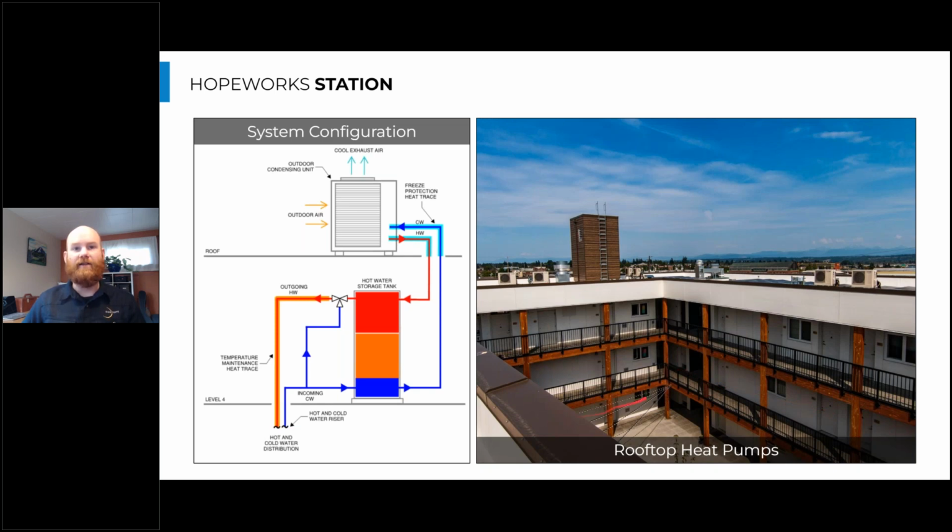So like I mentioned, there's 3 stories of residence, and this heat pump water heater here is serving vertically 3 units, which is about 6 people, 4 to 6 people in total, depending on if those are 1 bedrooms or 2 bedrooms or studios. And we repeated that across the entire building, putting numerous of these heat pump water heaters on the rooftop and serving in vertical piping sections.